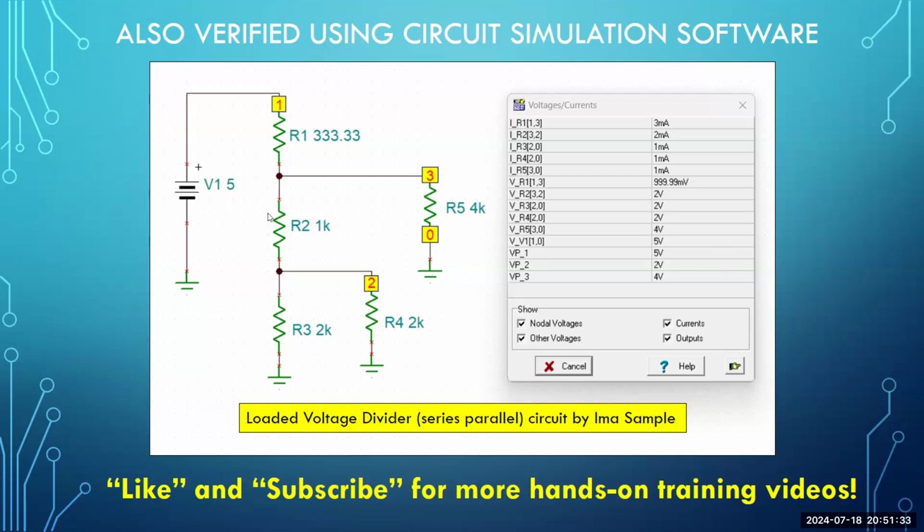Take a look at the voltage across R2. We anticipated we needed 2 volts. So VR2 is 2 volts. VR3 was needed to be 2 volts. VR3 is 2 volts. VR4, the load resistor number 4, required 2 volts. So VR4 is 2 volts. VR5 load resistor required 4 volts because it was attached to point B. So VR5, take a look at VR5, 4 volts.